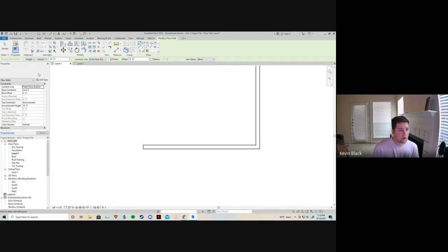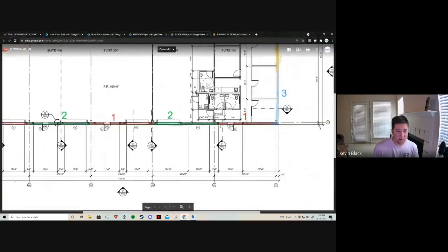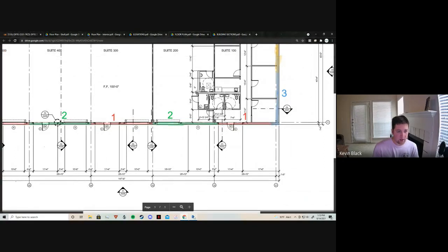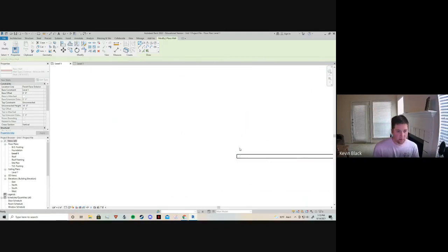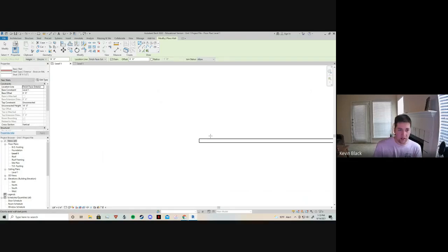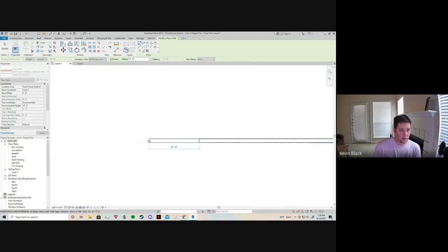And then from there, that's when we're going to use the actual dimensions given to us, that 28 foot 10. We don't have to do any math from there on out. As you can see, those dimensions are rooted exactly to the wall ends. And we'll just alternate between wall type 1 and wall type 2, finishing off those dimensions. 28 foot 10. You can see Revit snaps really well to the 90-degree marks, the 90-degree points, so we can draw pretty consistently in a straight line.